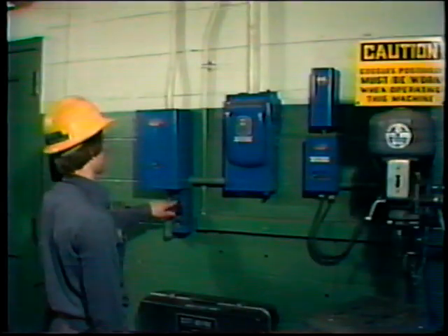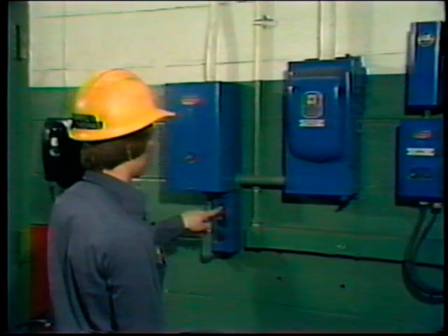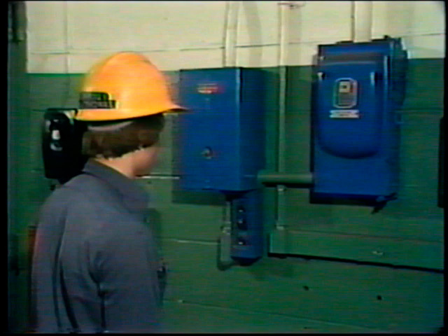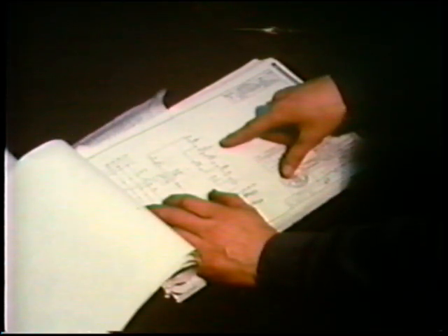After discussing the symptoms with the operator, the electrician test runs the motor to verify the symptoms of the controller problem and determine if any other symptoms are present. During the test run, the electrician can hear the contactor close when the start button is pushed and open when the start button is released. So the main contacts are operating. Once the symptoms of the problem are known, the electrician evaluates the problem by referring to the controller's schematic diagram. The most difficult part of his job is about to begin.